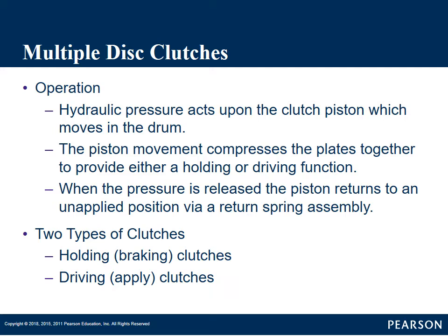There are some transmissions that also apply pressure on the front side of that piston to help push that piston back. Again, it's just to assist in releasing that piston faster,